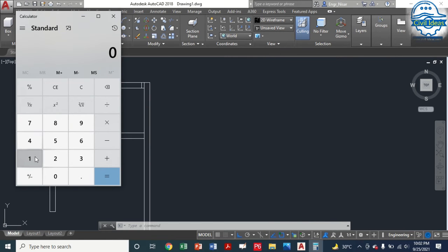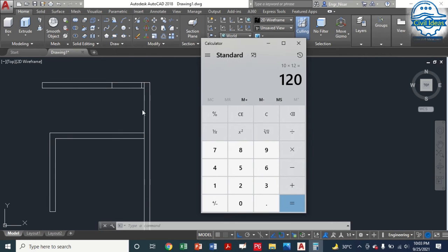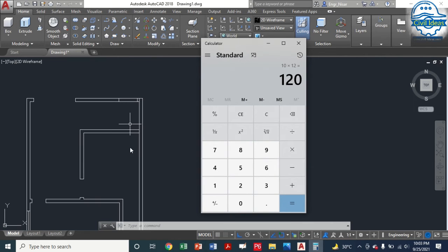So now there's 10 feet, this is the story height, multiply by 12, we have to convert into inches, 120. Now we'll divide it. If we provide a 6 inch rise, or 8 inches rise, because this space is very low.